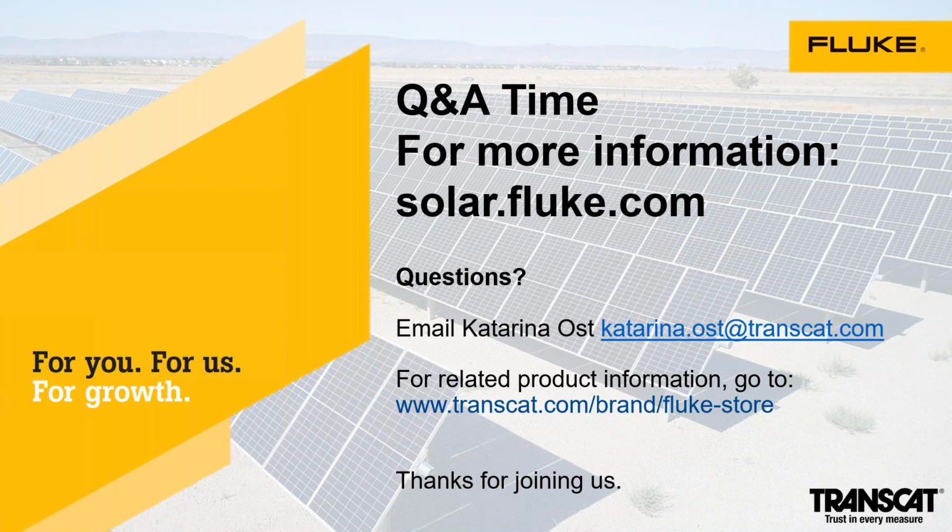Here's one. Doesn't the 1500 volt meter come with 1500 volt rated test leads? How would you end up with leads that didn't match the 1500 volt rating? Yeah, the 393 does come with the 1500 volt rated test leads. And I kind of touched on this in the presentation. The most common way is someone misplaced the test leads or damaged the test leads that came with the 1500 volt rated meter and just grabbed some leads that happen to be sitting around.